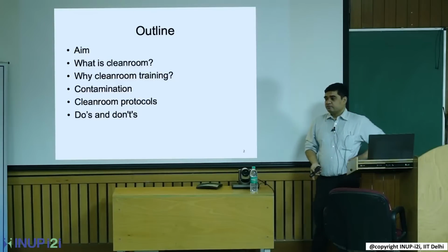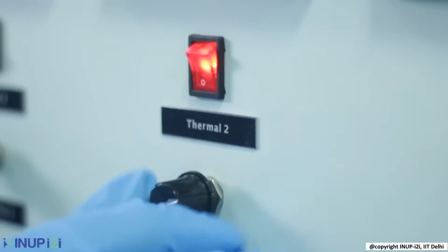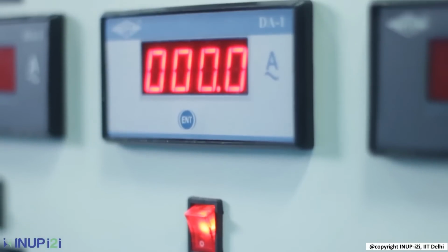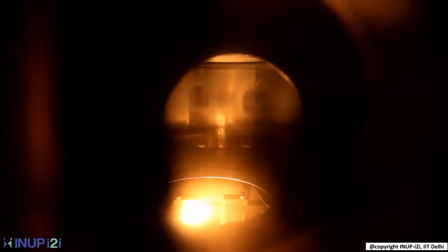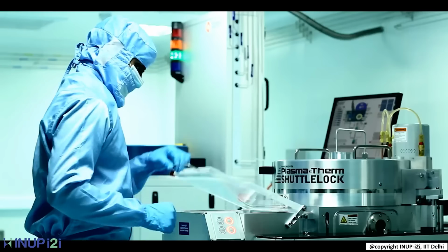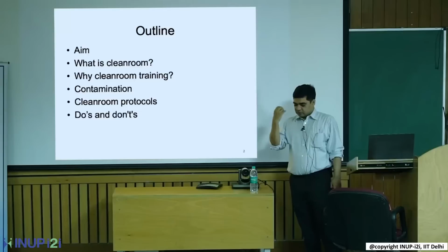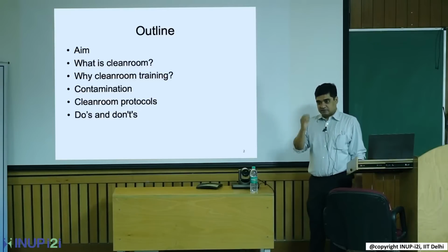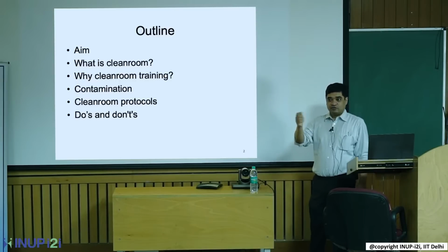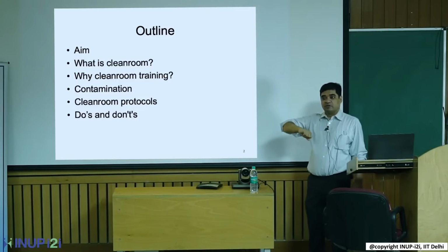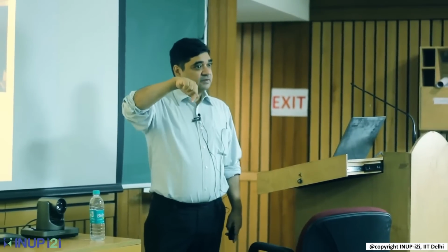The reason is that whenever you deposit a thin film on any material, whether you like it or not, there is always some native film deposited on it, because of oxygen in the environment. So that is one thing. The other thing is there are also a lot of contaminants on it. At all times, we are outgassing body odor and a lot of these chemicals, and if you are working with a silicon wafer, where do all these organic molecules end up? They end up on the surface of your wafer.